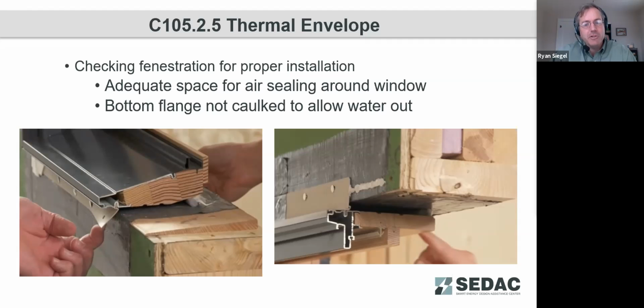Our exterior seal is predominantly for bulk water, trying to keep bulk water out of the assembly and out of our building, and then an inner seal that is used for moisture and air. So our vapor and air barrier seal is to the inside of the frame, and our bulk water seal is on the exterior.